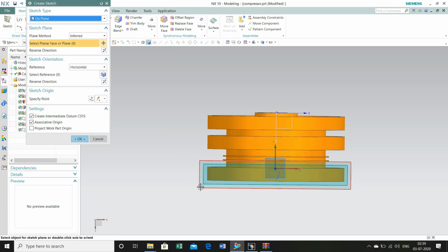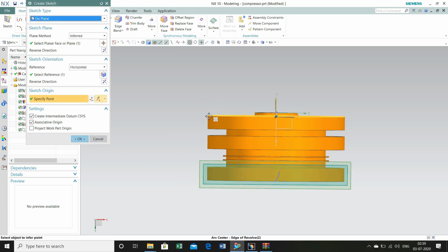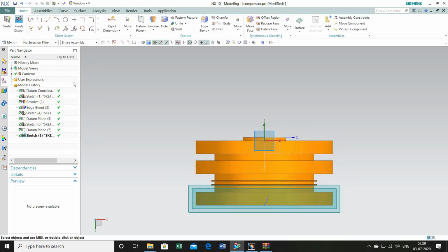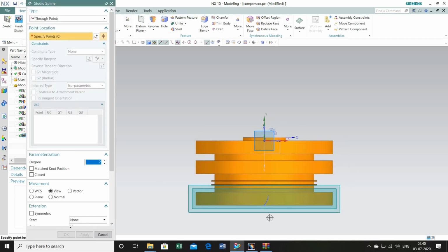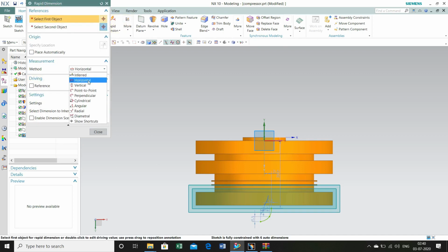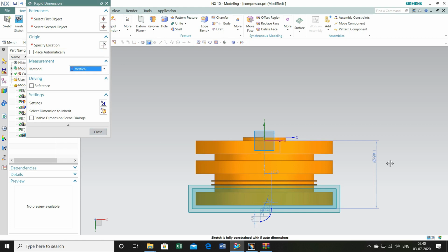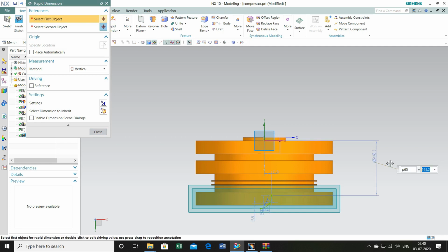Okay. Now again select this sketch for the sketching and shift the origin to the previous location. Okay. Again draw a spline with 3 control points. The degree of the spline is same as before, 2. Define the dimensions. This dimension is again 165.2 mm. Second control point is 181.2 mm in the -y direction. So the last control point is 195 mm below the x-axis.